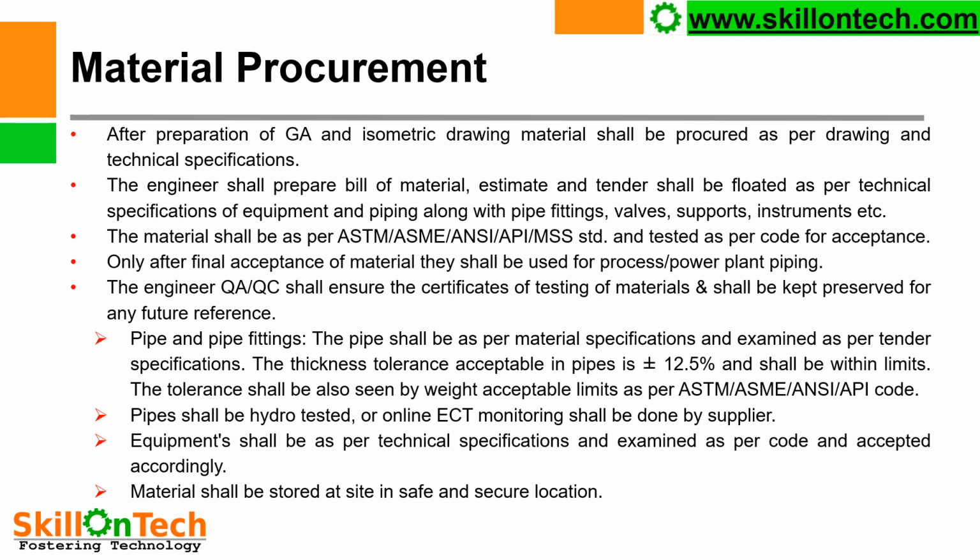The quality assurance or quality control engineer shall ensure the certificates of testing of material and shall keep them preserved for any future reference, because they are very important certificates and they shall be required later on, after the completion of the project, during the service of the pipeline. So they shall be preserved.